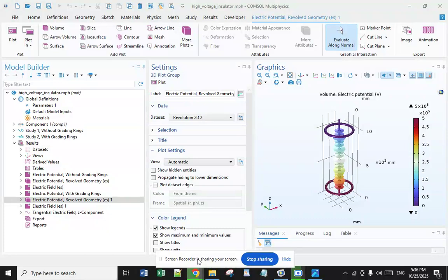And what about the aging and deterioration? Over time, all insulators undergo a process of aging and deterioration. Continued exposure to the environmental and electrical factors mentioned above can accelerate this process, compromising the insulator's ability to function effectively. Material degradation, whether through erosion, cracking, or loss of dielectric properties, is a critical aspect that must be monitored.